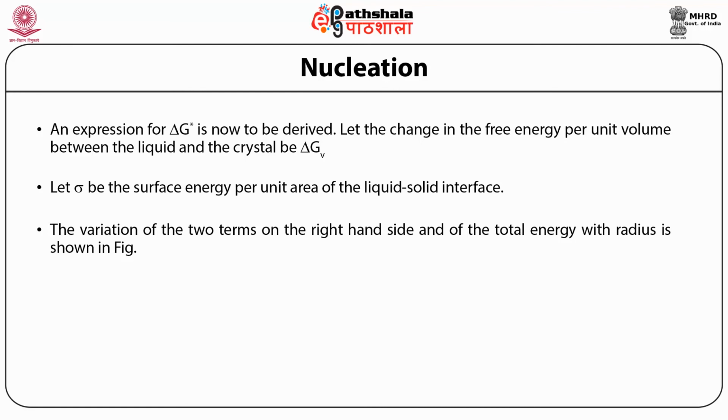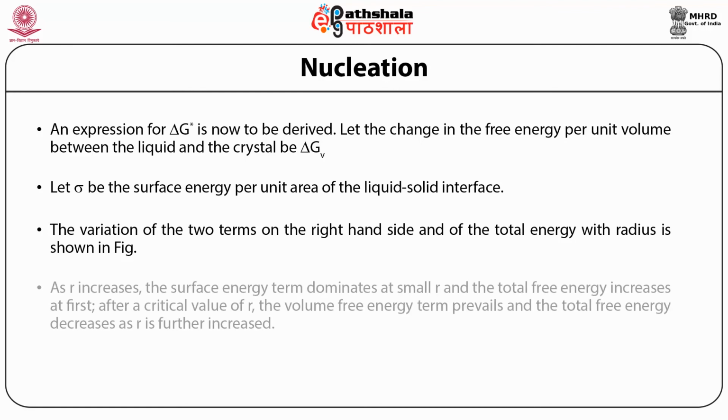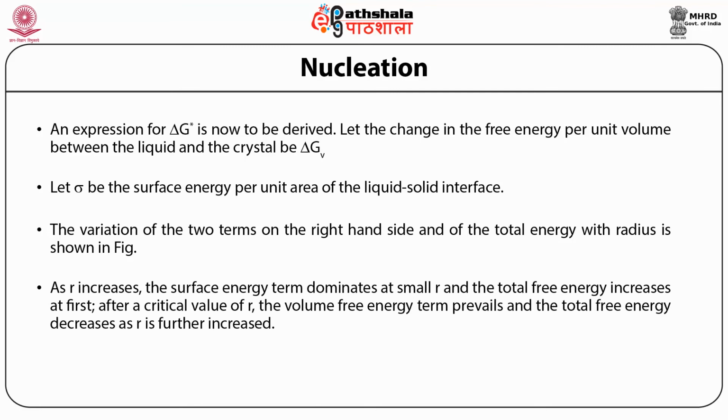So from this figure, it is clear that as r increases, the surface energy term dominates at small r and the total free energy increases at first.